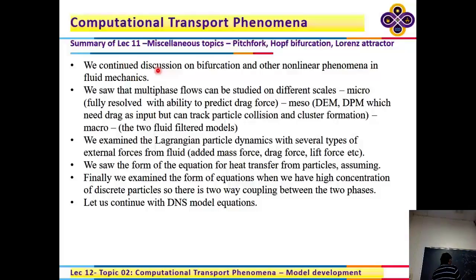So if this is long enough, and you take a region here, that will be very close to the solution you get for the one-dimensional case. But as you approach this wall, you have to have a no-slip condition. It will impose a no-slip condition, and that would mean that the fluid velocity here is lower than this. Right? And that creates a centrifugal force differential. So what will happen is you will have some sort of a weak cell, always, no matter how slow the rotational speed is.